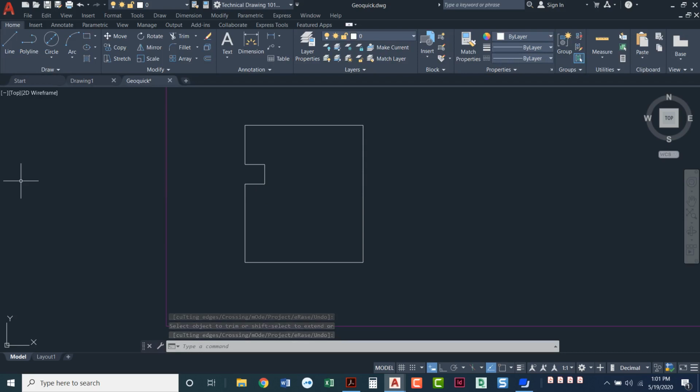The next step that we're going to do is start the circle command. One thing I've noticed, I can't start the circle command until I turn on my O snaps. I need to be able to snap from a corner. So my O snap icon is down here. I'm going to click it to turn it on. You can also press F3 on your keyboard. Watch this button and you'll see it turn off. F3, F3 to turn it back on. It's on when it turns blue.